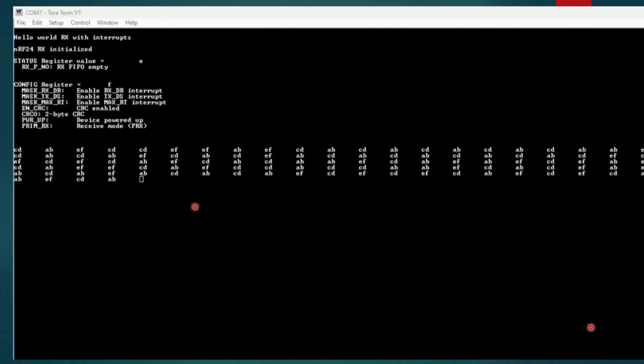If you get nothing, then you go back to your program and you're going to put a whole bunch of dump data. So every time it goes through the loop, you're seeing whether or not there was anything on the buffer or what happened. So this gives you a fighting chance getting the status register and the config register.